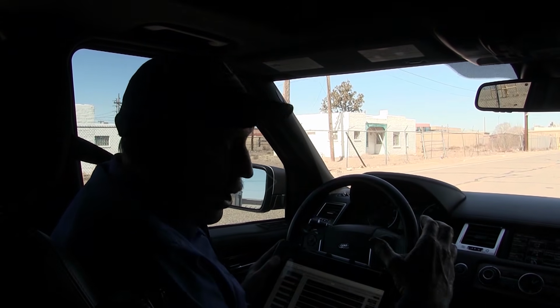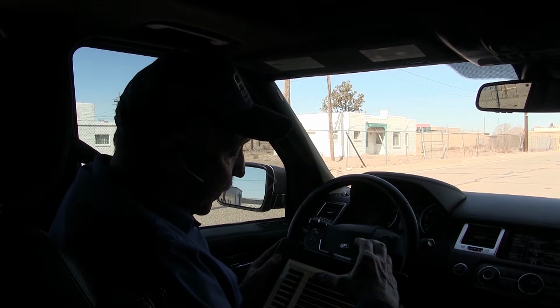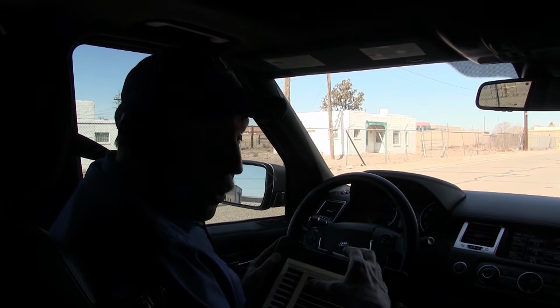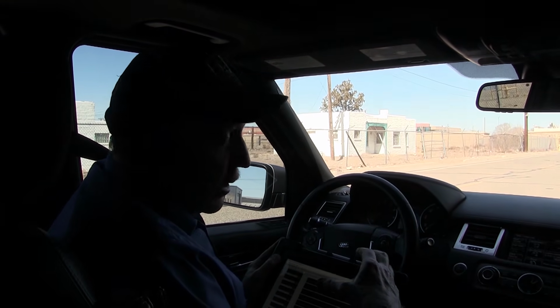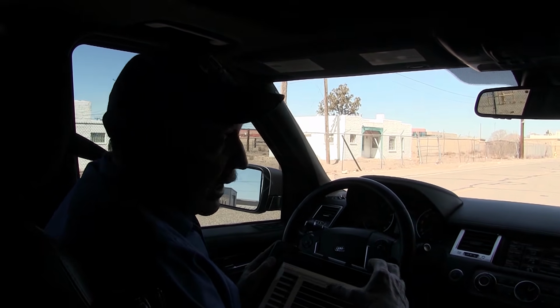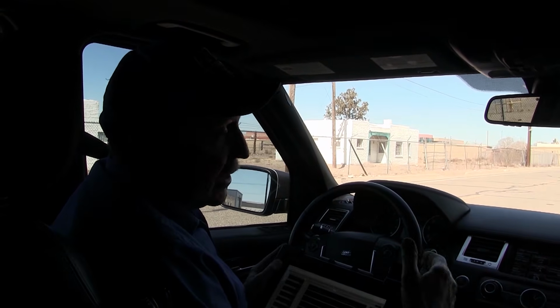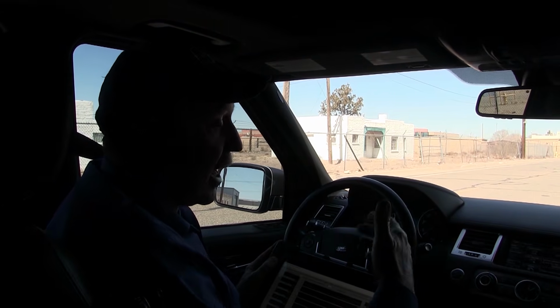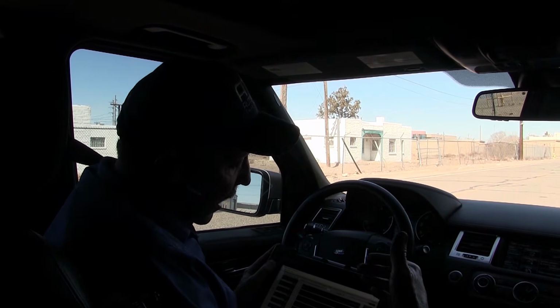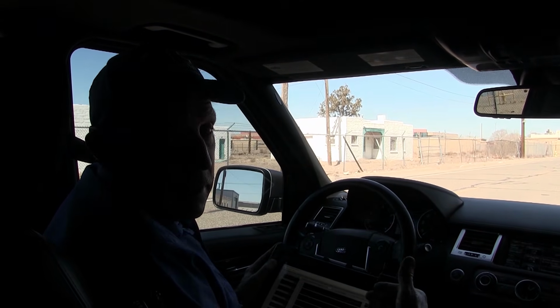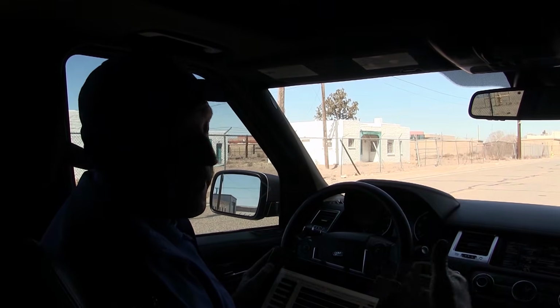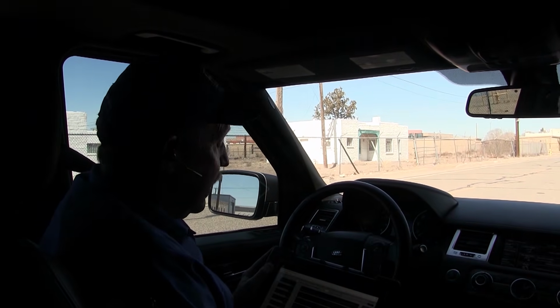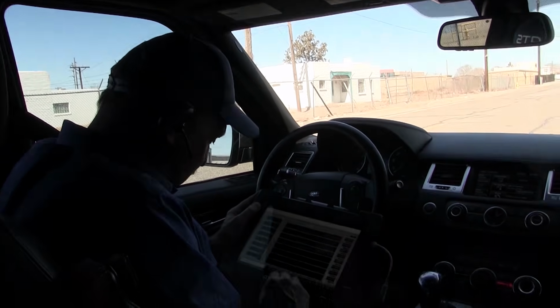We now know that the fuel that's delivered and burned stayed correct. We have a lambda of 1. So basically the computer is doing everything it can. It's not on the air side and it's not on the feedback side. So this problem is on the fuel side. It's a delivery problem.